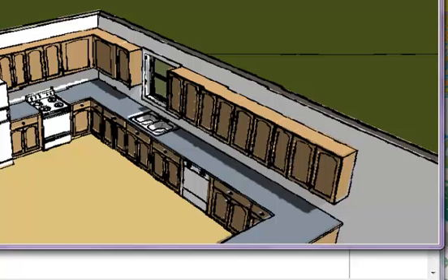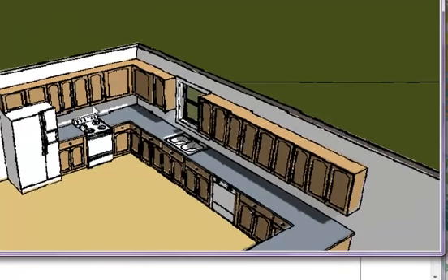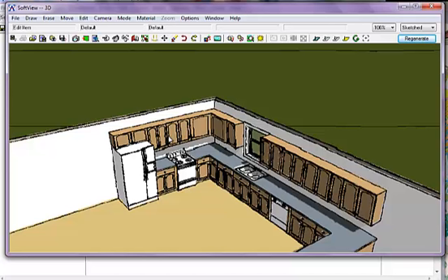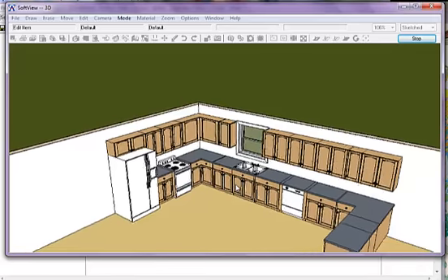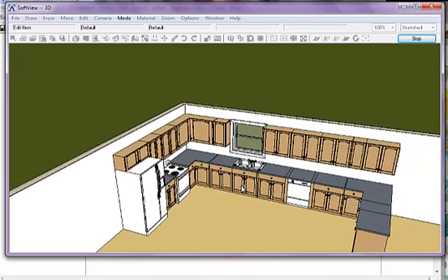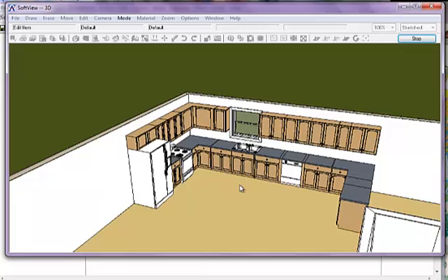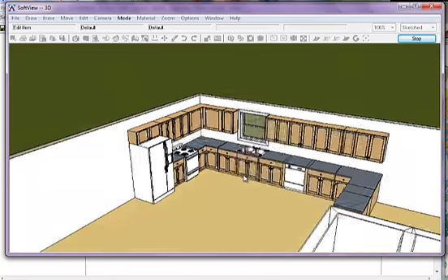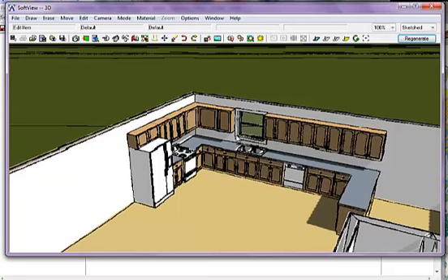Again, for the cabinets above the fridge, all I did was just edit their height, and similarly you could edit the height of the cabinets above the stove and then insert a symbol for the stove vent and set it so that its height is up at the right level, and it'll look perfect in there as well. So those are some things that you can do in order to improve the look of your kitchen layout and work more towards a level 4 evaluation.